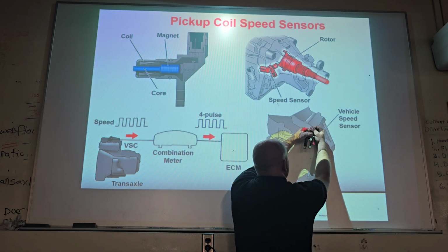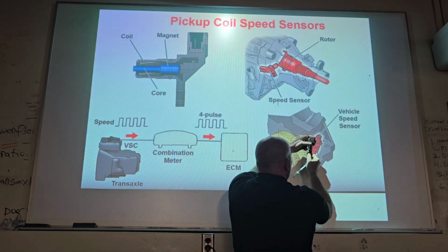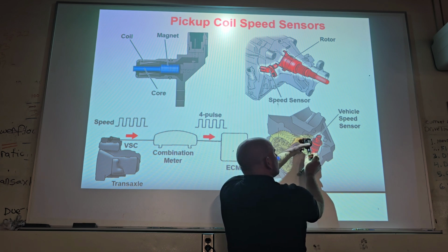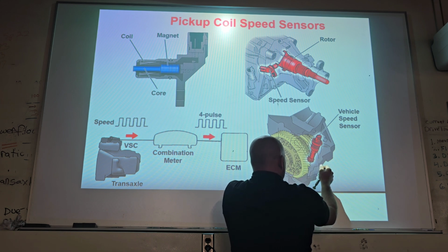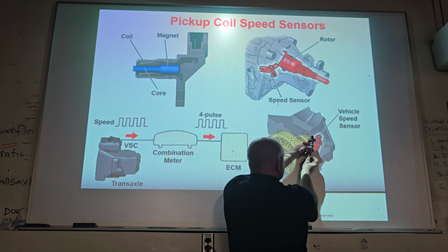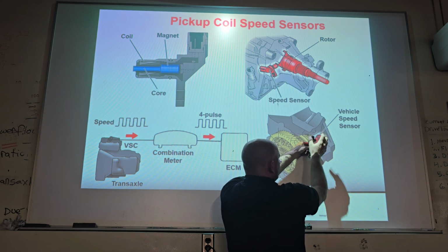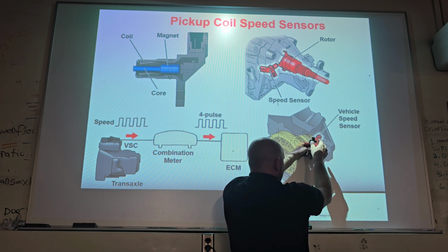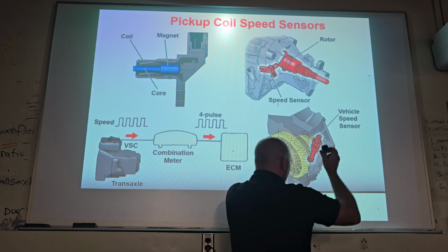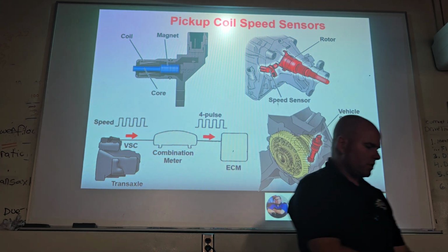Kind of the same. One's a little more worn. They had the bottom of the governor, which this one's worn. This is called Apple Core wear. This governor is shot, but the governor would spin, and then they said, forget that, we'll put a speed sensor in there. It looked the same and worked the same, but rather than spinning weights, this same little plastic gear would spin and it would generate a signal on this vehicle speed sensor.